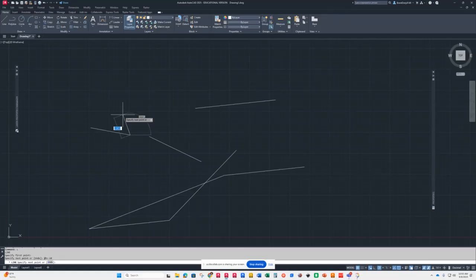All right, well, I can also do this. I can do line, pick, I can do shift at, and then put in my distance, and then do shift, comma also, and it's still going to be a relative polar command. So what I'm trying to get across to you is pay attention to your pointer right there.